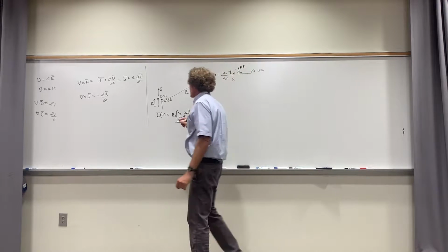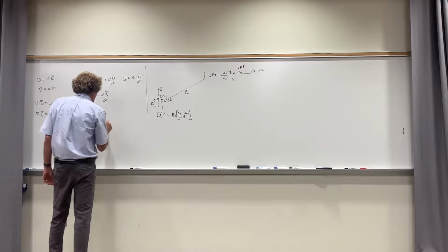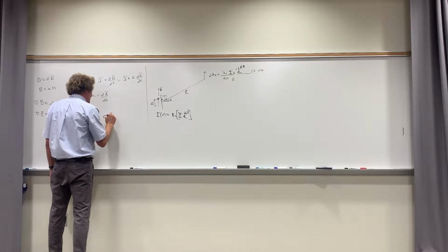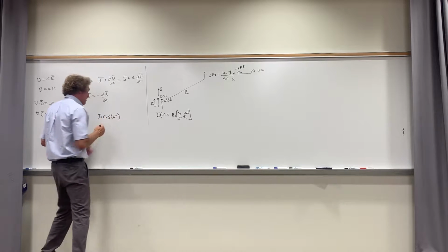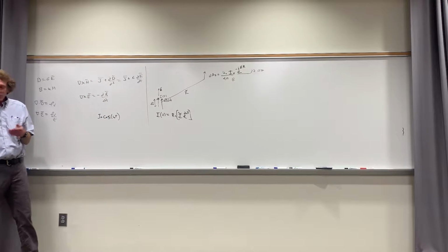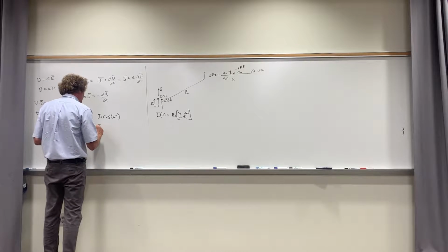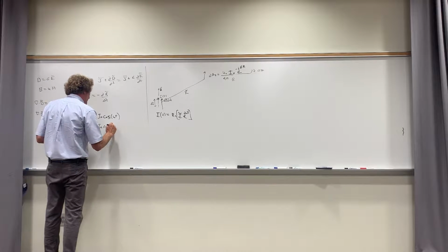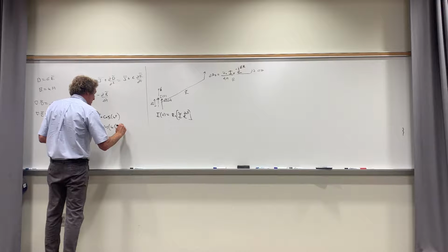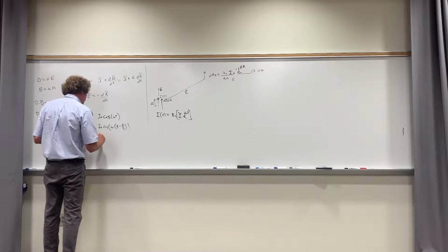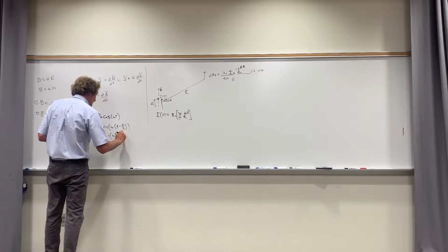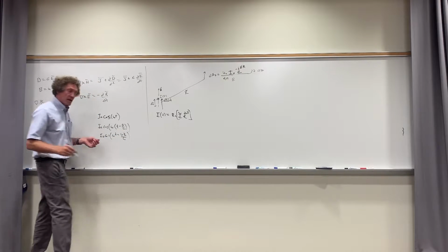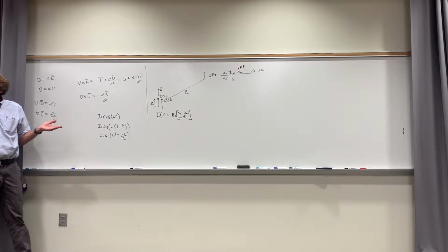It's just a phase difference. And the reason it's the case is normally you're used to seeing cosine of omega t times I naught. That would be a current. Do you agree with me? Well, if you put the time delay in there, then it would be I naught times cosine of omega times quantity t minus r over c, or I naught times cosine of omega t minus omega r over c. And omega over c is beta. Y'all follow me there, class?